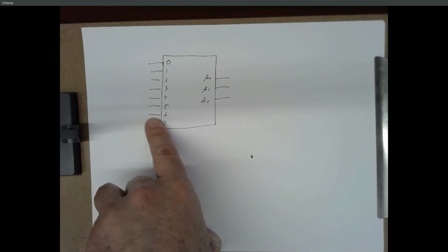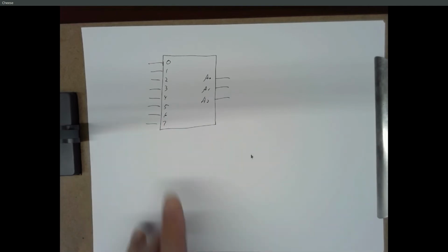This line might say the power is failing. Well, power failures are pretty bad, but for a CPU, you can do millions of things before the power actually goes away. Because when you unplug a computer, it takes a while for the charges to dissipate, and there's enough time to actually do some stuff. So that's going to be a pretty high priority event. But you still want to know about it because you can do things like park the hard drive or save some critical information and so on.